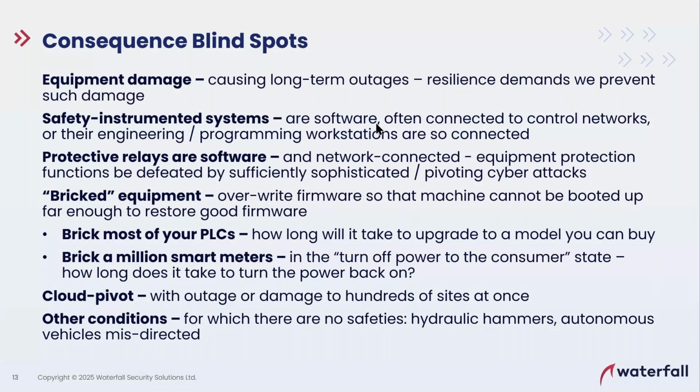You can't repair it. If I have an air conditioning unit in a high rise and I run it at full speed, absolute flat out, for a whole weekend, I destroy it. How? I'm running it faster than the water can move. These things have a range of speeds. I run at full speed, and you wind up with tiny vacuum pockets behind the blades because they're moving water around to cool things off. And these vacuum pockets collapse and send out shock waves through the water. Water is a very good conductor of shock waves.